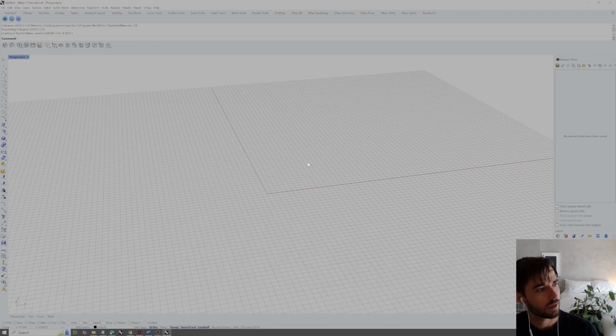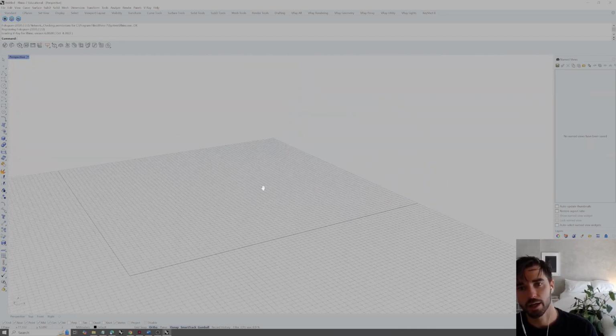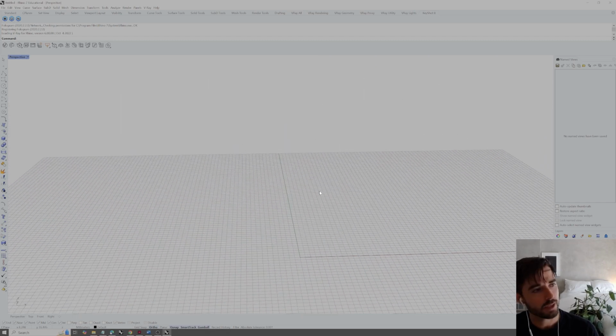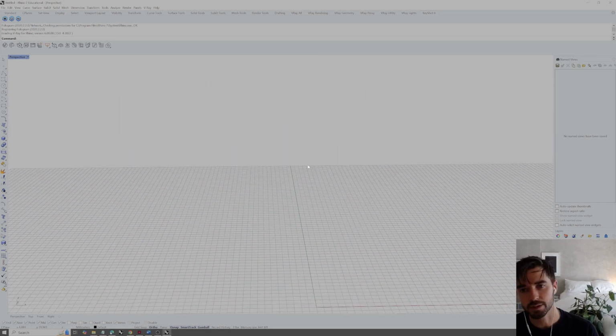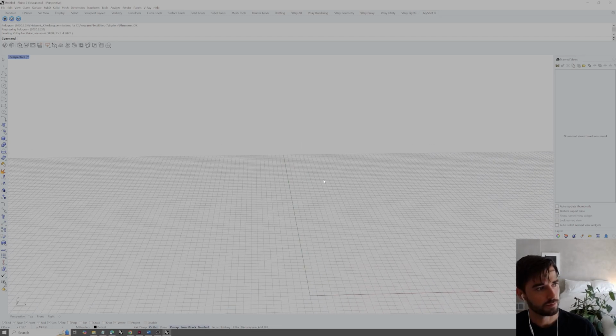And then I can hit control alt, right click and drag, and this allows me to pivot. So this is a pretty crucial thing for architectural perspectives. If you know that you're on the exact viewing point that you want, but you don't quite have that perspective angle set, this can be a really great tool for navigating around your scene. So control alt, right click and drag is a kind of pivot view.